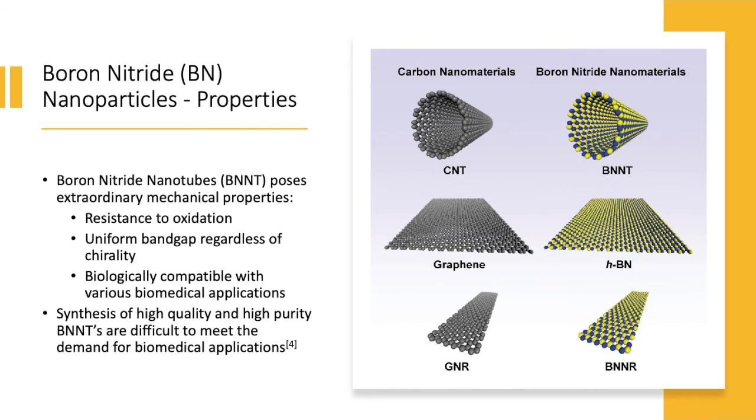Some properties of boron nitride are that it possesses extraordinary mechanical properties. Interestingly, it also has resistance to oxidation, a uniform band gap regardless of chirality, and biological compatibility with various biomedical applications. However, synthesis of high quality and high purity BNNT, the nanotubes, is difficult to meet with demand for biomedical applications. That's why they're not regularly used within the biomedical community, because they are so difficult to synthesize.